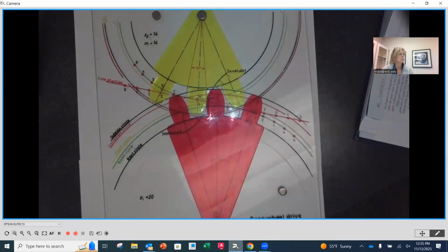Like the original part might have been 20, but when they replace it, it's 14.5? No. It means that in the past, they used to design with all three, and there is existing machinery out there that has 14.5 pressure angle. The only time we make 14.5s is for that existing equipment. Any new designs, we use 25 or 20.